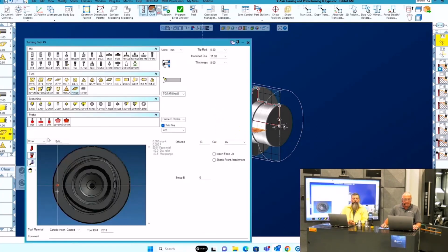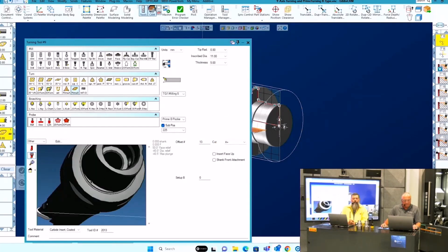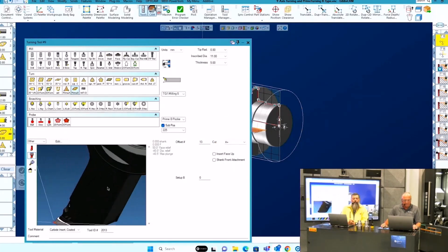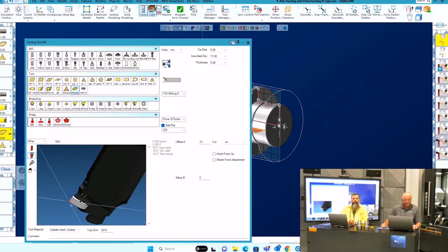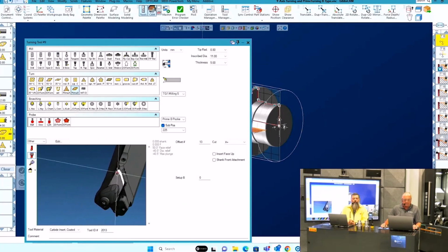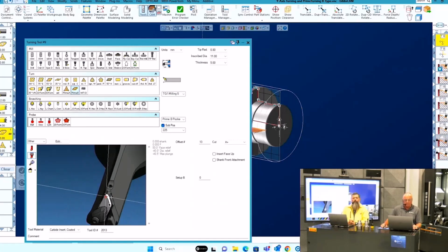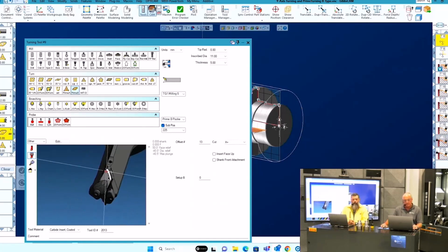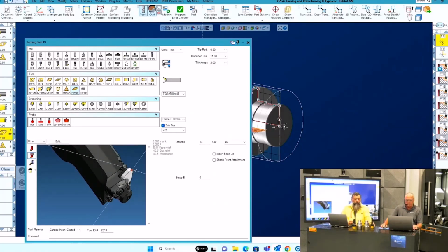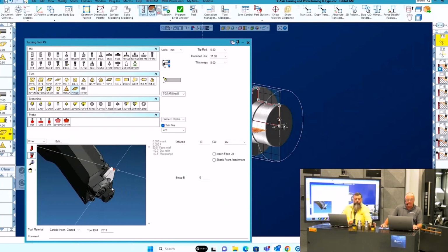Now I have selected a tool, and I'm looking in this case at our prime turning insert, the B style, second generation prime turning insert that we are using with y-axis turning. And here is the combo tool that Keith had mentioned earlier. That's tailor-made, but on request, of course, it's available to the user. And that's what we have here right now.